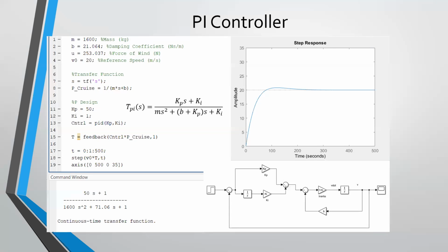The integral gain controller, however, also incorporates an overshoot. This wasn't a major issue, however, in fact, it was actually preferred to the design. With the overshoot, it allows the vehicle to go past the reference speed, which would allow the vehicle to upshift if it was necessary before returning back to cruising speed.